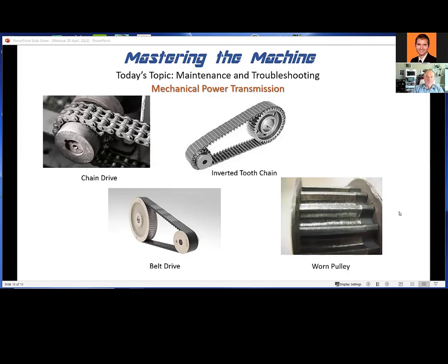Whereas something that needs very instantaneous analysis or some type of outcome very quickly, based on what that computer vision system is detecting, you may want to do that at the machine level or at the edge, on that device attached to the machine. The reason being, if there is a disruption in the internet, you wouldn't want some type of failure to occur because your machine vision application wasn't operating correctly.